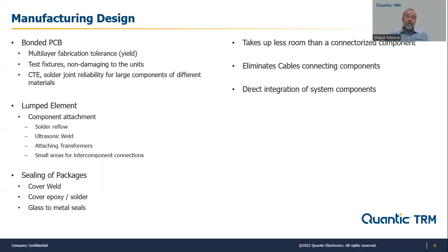Another challenge, which we always have to consider, is how we're going to test these. There are test fixtures. We have to be able to make momentary contacts with the units that have good 50 ohm transitions without soldering the parts down. So that is indeed a challenge. And also, as we get larger and larger circuits, we have to make sure that the CTE of the substrate that the device is made on and the mating PCB that the customer is mounting it to balance.